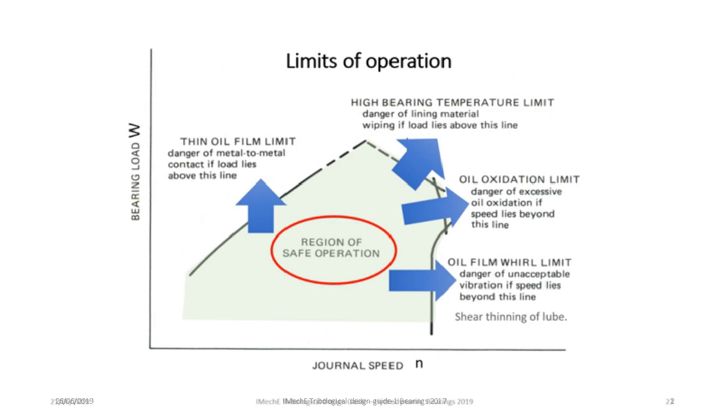At modest loads but high speeds, there can be dynamic instabilities in the oil film, leading to the initiation of vibrations. In addition, the very high shear rates imposed on the oil can lead to a reduction of its viscosity as the long hydrocarbon chains are broken. Increasing load and speed together will mean that more energy is being injected into the oil film, so that the temperature of the assembly will rise, perhaps to unacceptable limits, because of softening of the protective white metal layer or excessive oxidation of the lubricant.